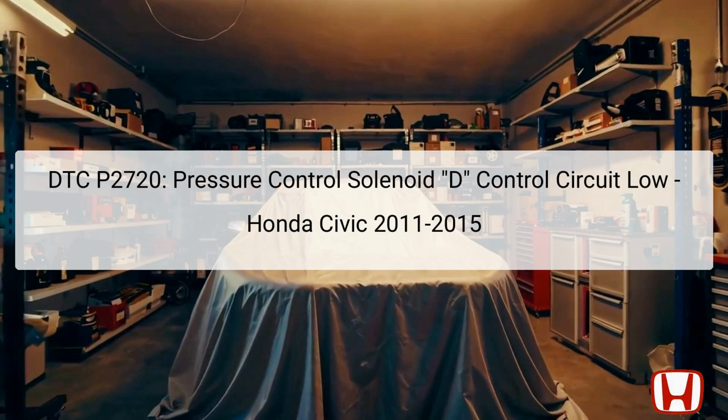The DTC P2720 indicates a pressure control solenoid D control circuit low issue, specifically in the Honda Civic models from 2011 to 2015. This particular error is related to the electrical circuit, specifically implicating a breakdown in communication, rather than a mechanical issue within the transmission system. It's crucial for the vehicle's engine and transmission to communicate effectively to manage power efficiently.